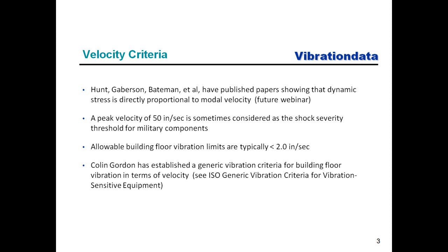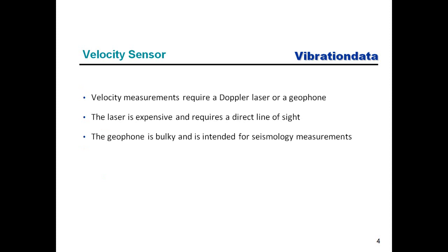So if you were out measuring the floor vibration in a building or a historic site or a factory, then most typically you would use an accelerometer, but then that data would need to be integrated to get the corresponding velocity so that the resulting velocity could then be compared against some standard or specification in terms of judging severity.